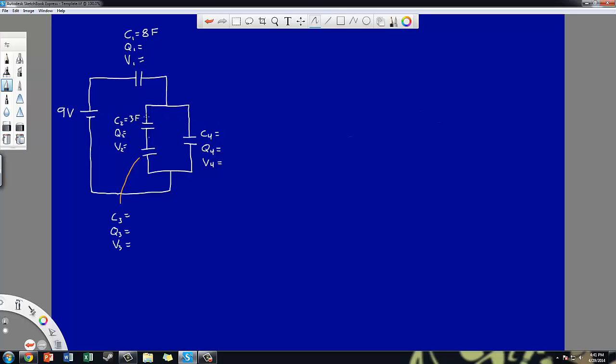Likewise, when I look at this little box here, this tells me that there's something parallel going on in this circuit, and I can see that on this side there's a connection, and on this side there's a connection. But if I look at the individual capacitors, capacitor number 4 is not completely in parallel with number 2, because while it shares connections on this side, on the opposite side it does not have a direct connection to C2. Instead, it runs into C3.